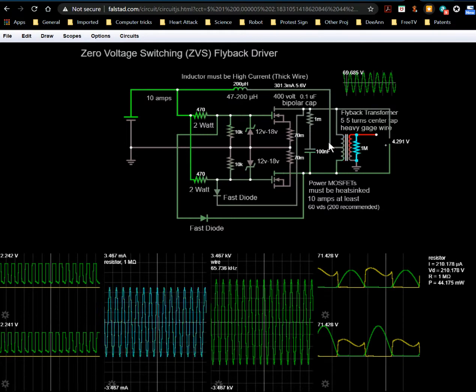And it literally works, and this is what always confused me, but I realized that until this capacitor is charged up, this inductor will keep dumping current into it. This is why inductors, like this choke, resist a change in current. When you first apply a voltage like 24 volts across this inductor, ignore the fact it's going to the center of this.